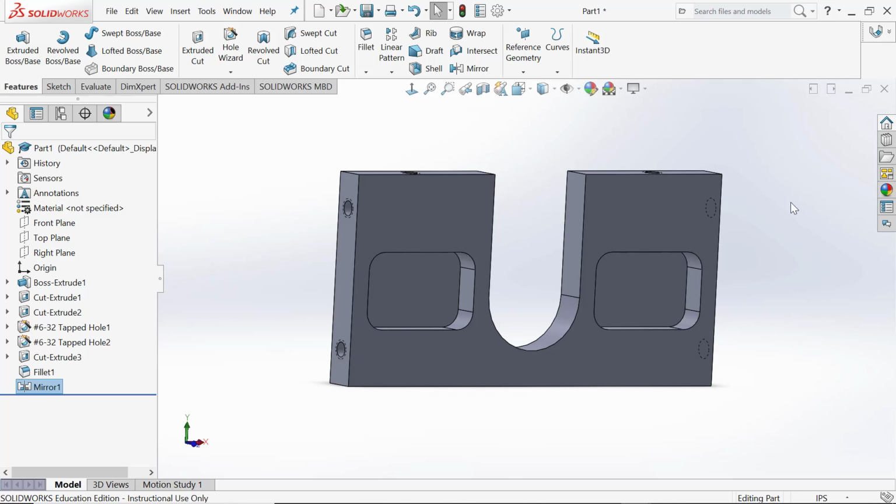You'll notice that generally speaking, what we did was we chose a surface by right-clicking on it and launched a sketch by clicking on the sketch icon. We selected a sketch tool, put it in place, and then exited that sketch tool. Then we applied dimensions and relations as necessary to get it where I want it. Once it was fully defined, I exited the sketch and immediately applied a feature. On the feature, I always was worried about the dimensions and the end conditions. When I got my dimensions and end conditions done right, then I exited that feature, and lo and behold, we had a part, right? Yeah, and it should go quickly once you know.